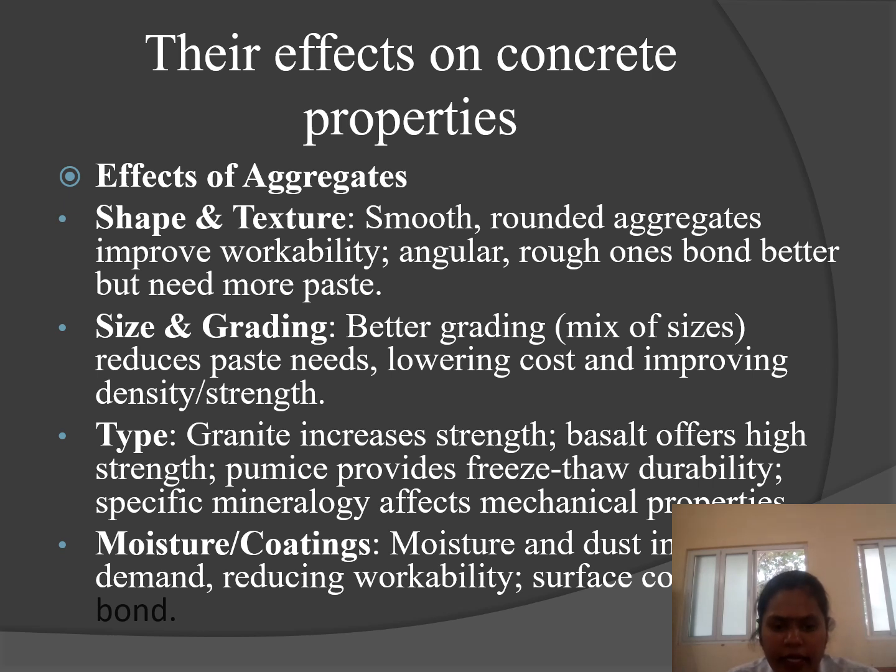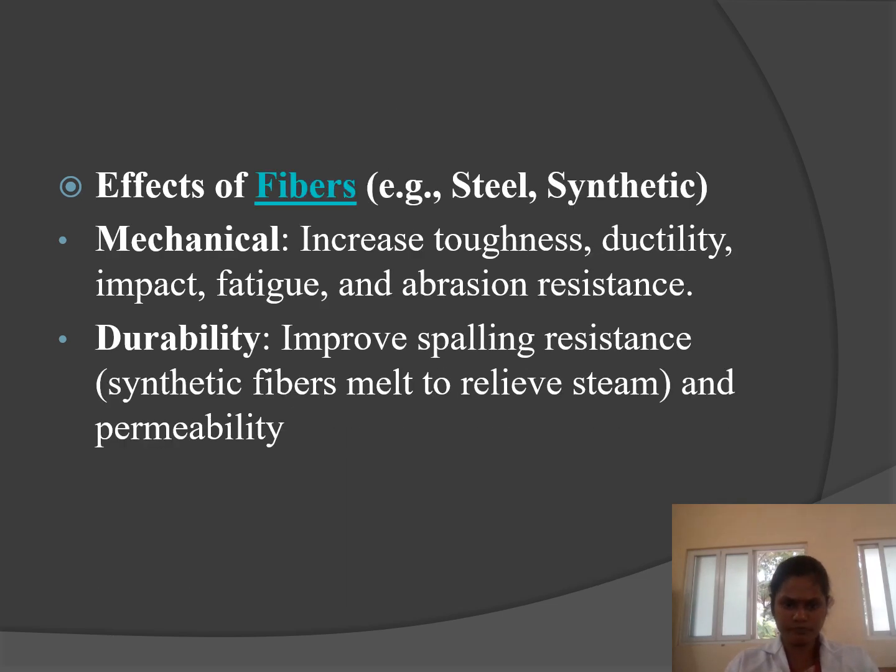Type: granite increases strength, and basalt offers high strength. Pumice provides freeze-thaw durability. Specific mineralogy affects mechanical properties. Moisture and dust increase water demand, reducing workability and surface coating bond.